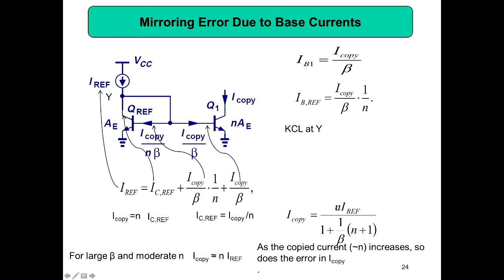It means if you are not connecting just one here, but maybe 10 transistors, because you are using maybe 10 times this current. Then from here you are tapping, again you get other branches, and you are using so many transistors here in parallel in order to make scaling. You know what I meant? If you are using so many transistors, what will happen? Your n equals a bigger value. When n is a bigger value, the error between your I copy and I reference will be more. Your I copy will be different from the I reference value.